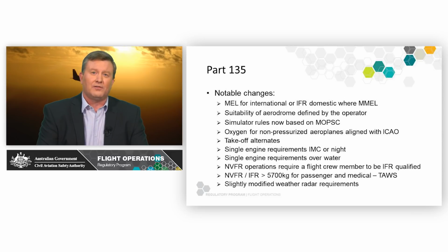So Part 135, I'm not going to touch on all of these right now, but these are some of the notable changes. There's a requirement for a minimum equipment list where there is a master minimum equipment list from the manufacturer for international operations and for IFR domestic operations. There's requirements for the suitability of an aerodrome to be defined by the operator with a list of criteria that the operator needs to establish.